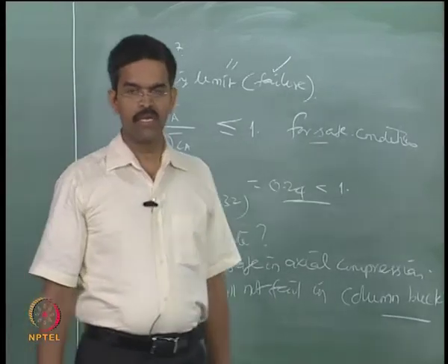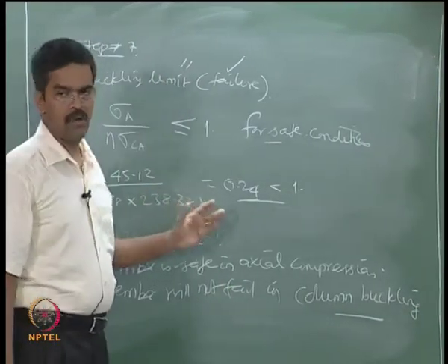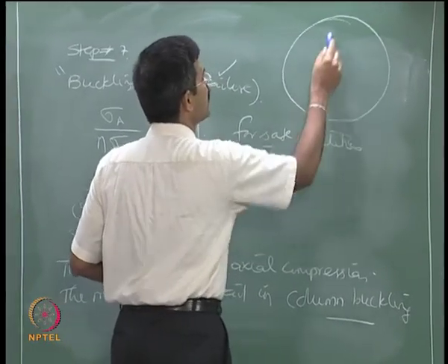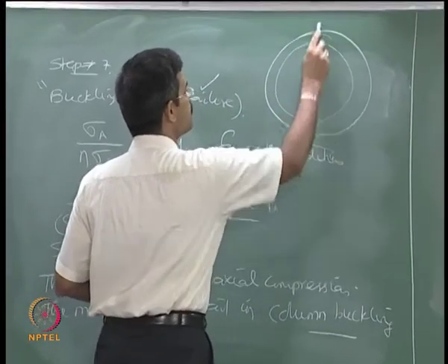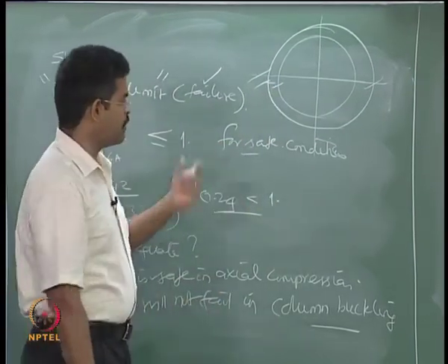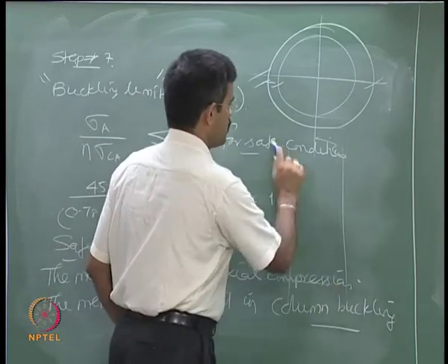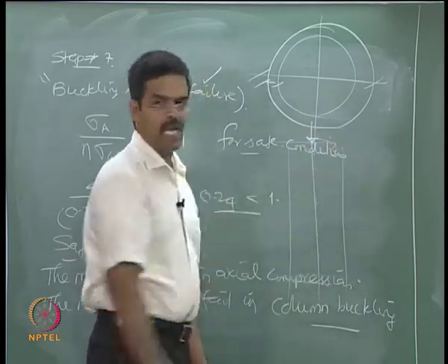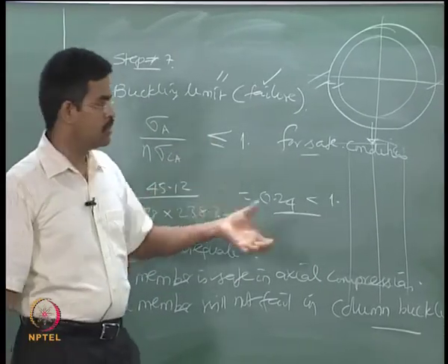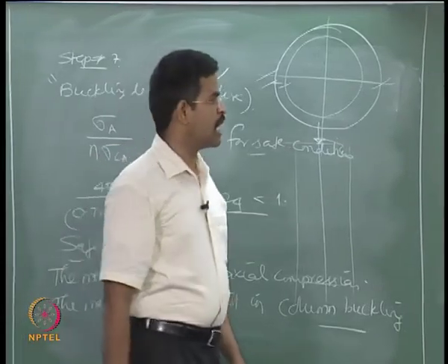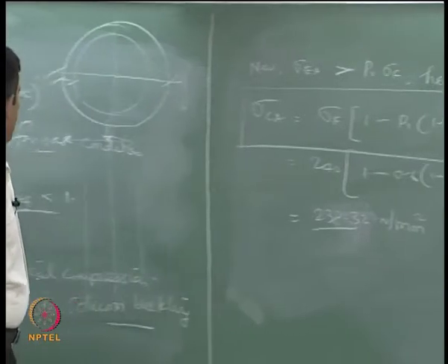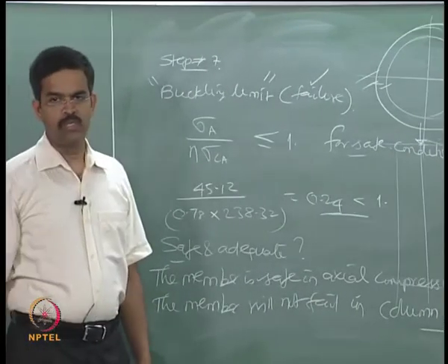Always in design it is only checking of the adequacy of the given member. Just for summarizing, you already have been given a circular member of a specific diameter and of a specific thickness for a specific load carrying capacity. I am only checking the adequacy of the member using a specific code. So, there are many empirical relationships being used in working out the adequacy.